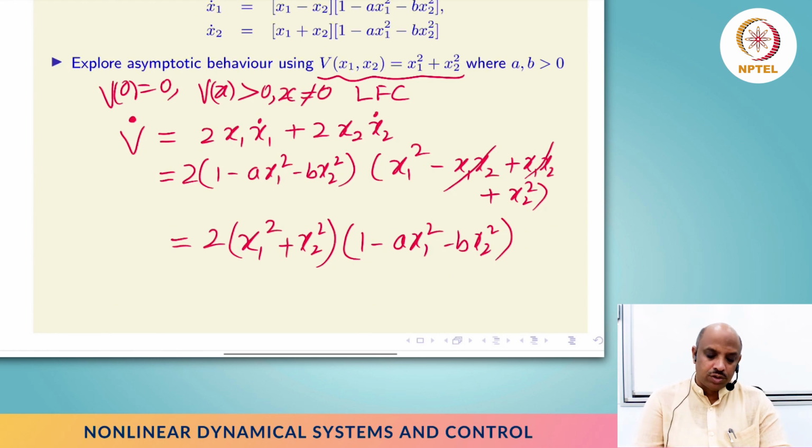Okay, and close to the origin, this is clearly positive, and therefore this system is most probably unstable. You know, we can actually use instability theorems to show that this indeed satisfies all the conditions of our instability theorems, especially the Lyapunov first instability theorem, which says that if we can find a V of x that has a positive point very close to the origin, and then we show V dot is positive, then this precisely shows that, right? What more can we say?